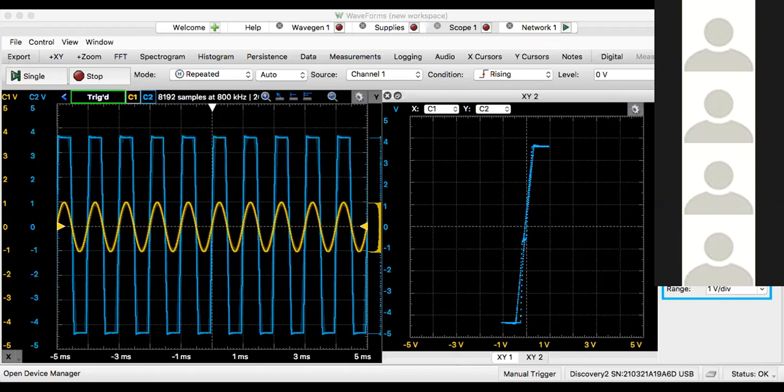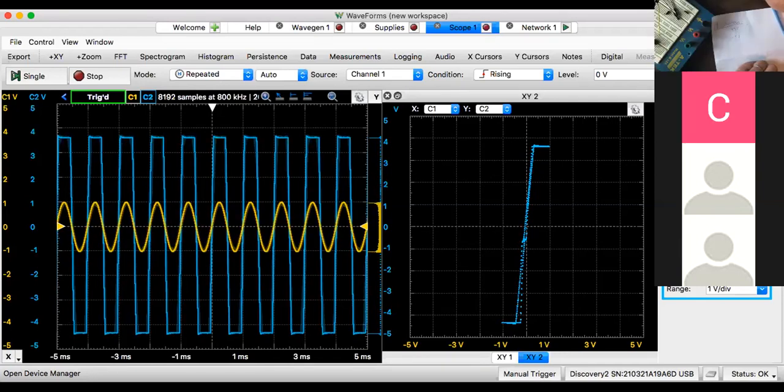The number 1 issue is saturation. It will saturate on both sides. Saturation on both sides. What is saturation? That means the power supply is positive 5 and negative 5. That's the power supply. And the output can never be bigger than this.